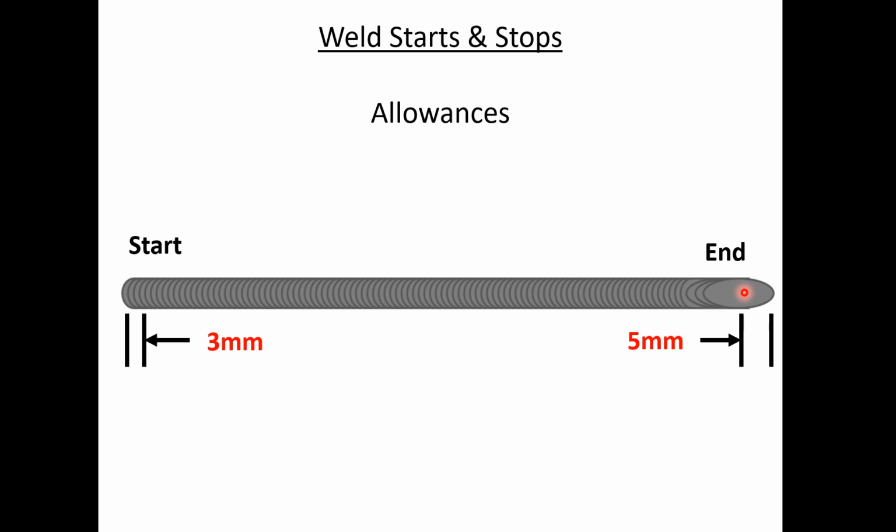Now, even in steel, it's very important in aluminum and all these others, but even in steel, you can't use your welding process to damage the base metal. So your crater can't be sunk in. It can't be down too low. It can't have edges on it. If it looks like a bowl when you're done, it needs to be fixed. That is, it needs to have some fill. The part of the weld that's measured is the length of weld that meets the spec. That's how simple it is.